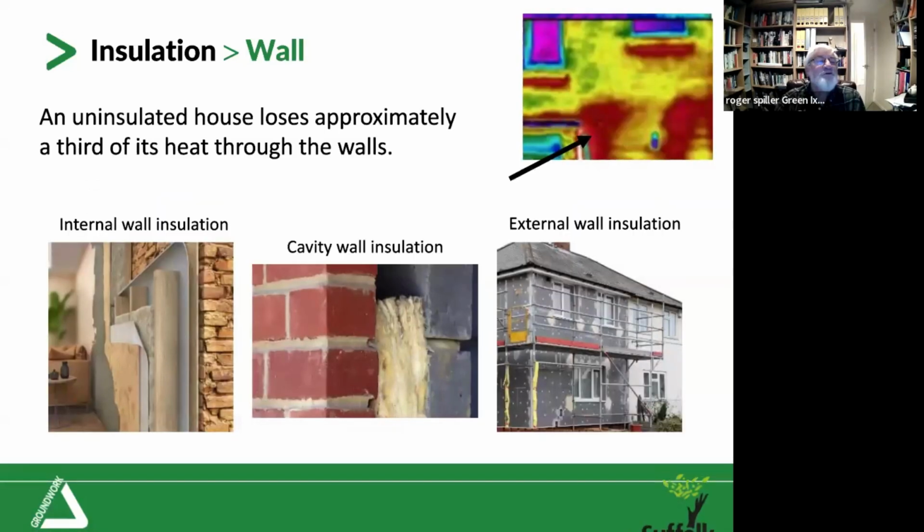Sorry, just before you do that, could you put out the warning that one of the problems with insulation is often dampness, the way it's used, and in particular the sprayed insulation that's been notorious in recent years for causing a lot of damp and actually destroying roofs. So I think it is necessary to warn people not to just go with somebody who comes along with what seems like an easy, quick and relatively cheap answer, as it can do a lot of damage to houses and make them impossible to sell.